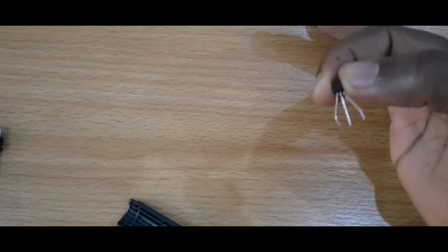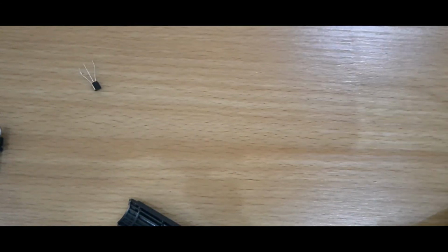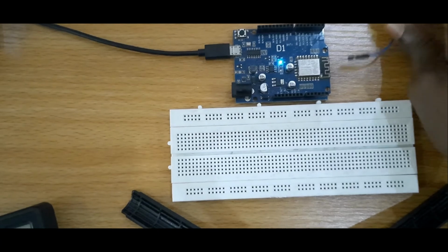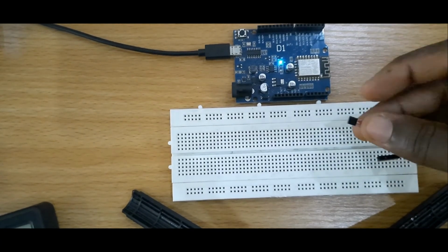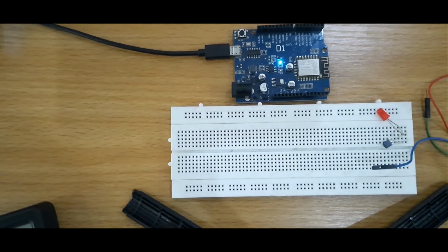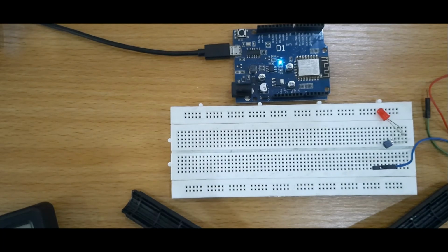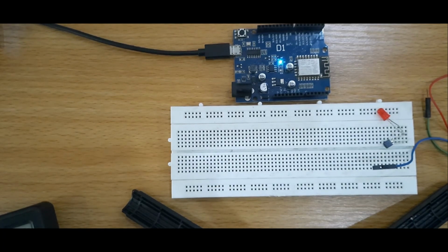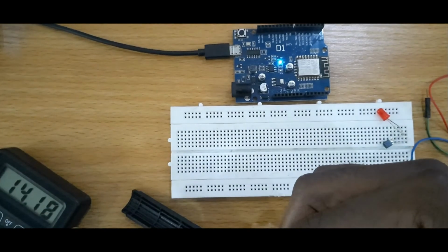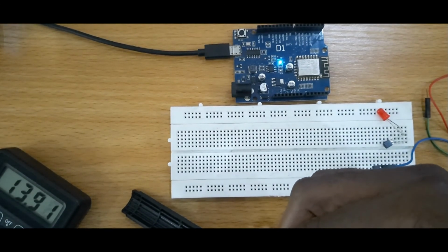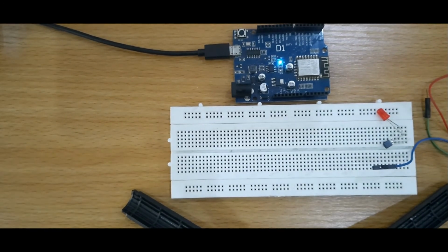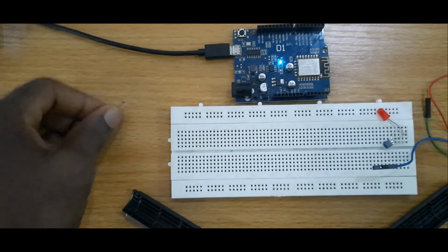Now let's connect it and see how it works on the Arduino. For this demonstration, I will be using a Wemos D1, some jumper wires, my BC547 transistor, and an LED bulb. I also need, according to our calculation, about 14,500 ohms. But I don't have that, so I have about 14,000 ohms, which you can see from my reading, about 14,100 ohms. So I will just go with that for now. Now that we have all the items we need, let's get started.